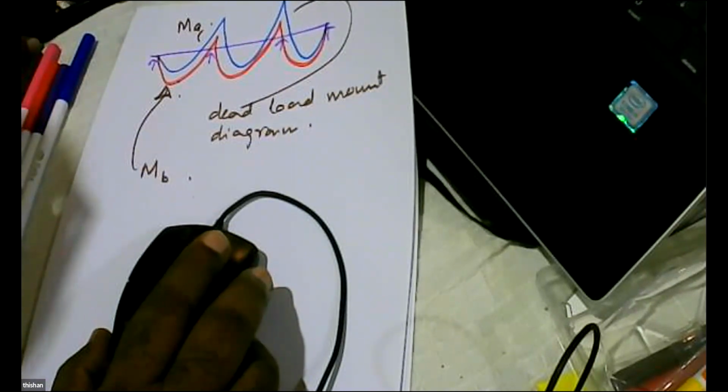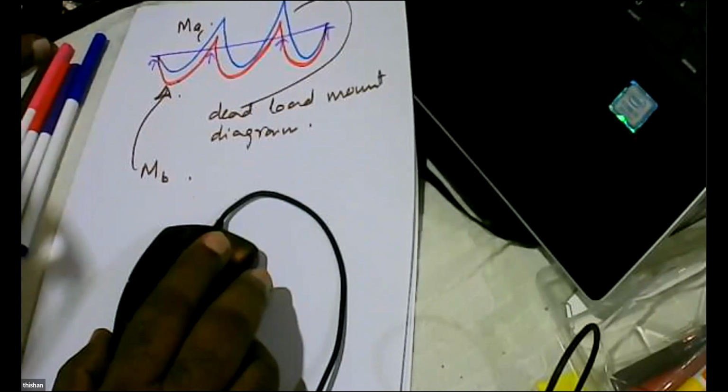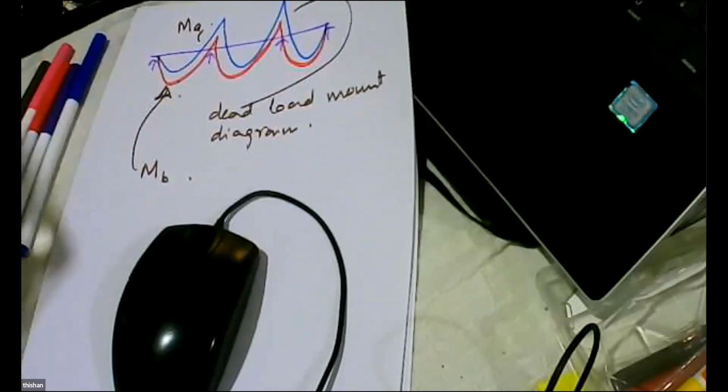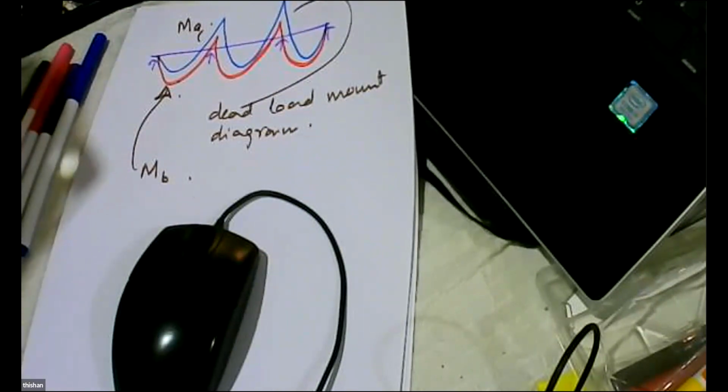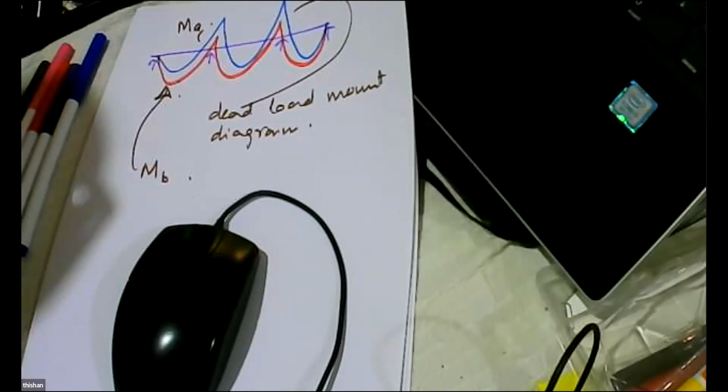Highlighting the proof, how I got this matrix. I used the matrix, but I did not show you how I got it. It's just a simple virtual work based theory that is very useful, so that's why I will show it. It can be used for creep and shrinkage calculations and so many other calculations. This method is applicable for any effect that is going to change the curvature.